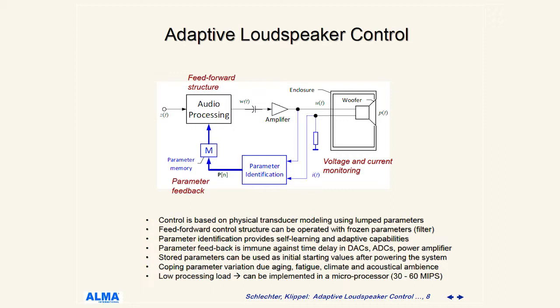The parameters can be stored in a memory and used for startup. They can be analyzed, they have a physical meaning, and this whole system can be implemented with quite low processing load, meaning currently it can be implemented on a microcontroller for woofer systems.